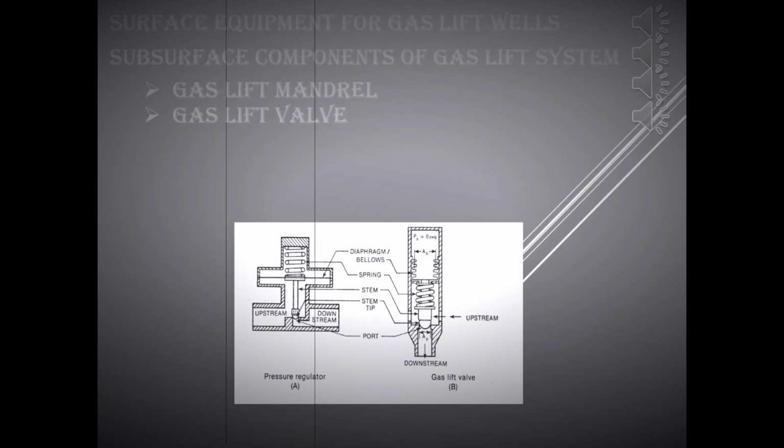For dually completed wells, tubing pressure operated valves are certainly better, with unloading valves as tubing pressure operated and the operating valve for both strings as casing pressure operated valves being a better proposition. Though, many a time casing pressure operated valves are preferred for dually completed wells.